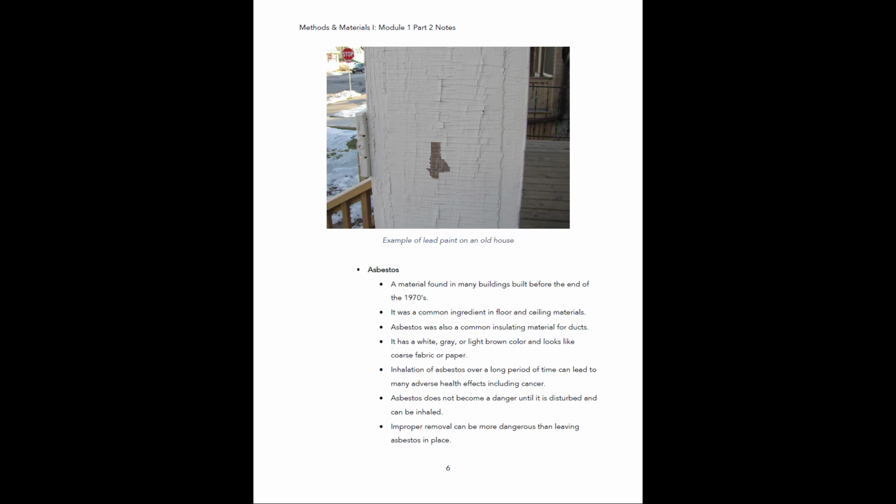Normally, the correct way to do it is to hire a specialized abatement team, and they're going to come in and go into hazmat suits and wear huge respirators and use a HEPA vacuum, all this complicated stuff, because whenever lead particles get into the air, that's when they become dangerous, because you actually breathe them in. So you don't really want to sand this or do anything that's going to turn into particles that you can breathe in.